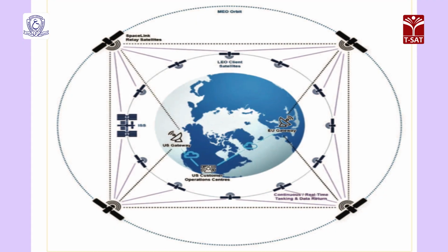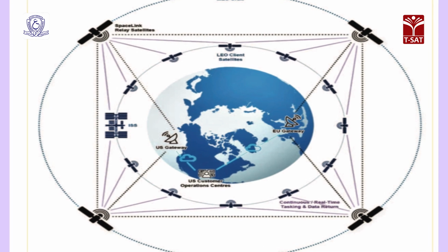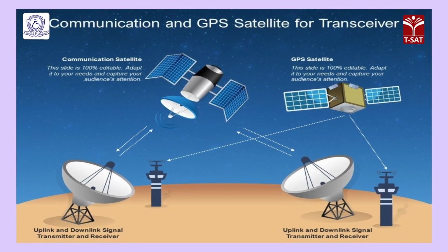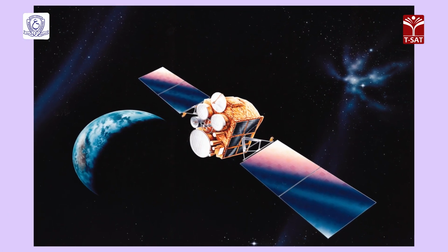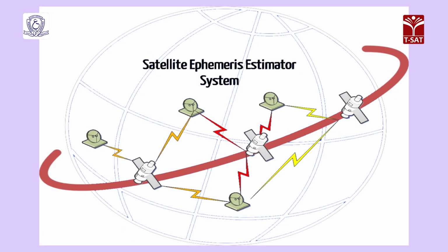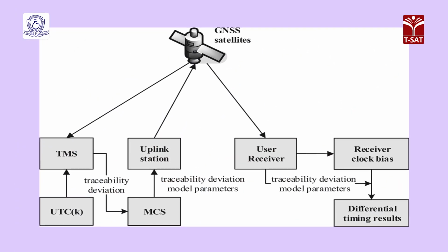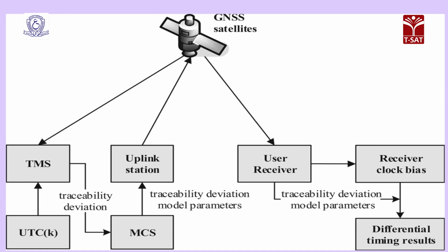The unmanned monitor stations passively track all GPS satellites visible to them at any given moment, collecting signals and ranging data from each. This information is then passed on to the master control station at Colorado Springs via the secure DSCS, Defense Satellite Communication System, where the satellite position, ephemeris, and the clock timing data, more about these in a later session, are estimated and predicted.